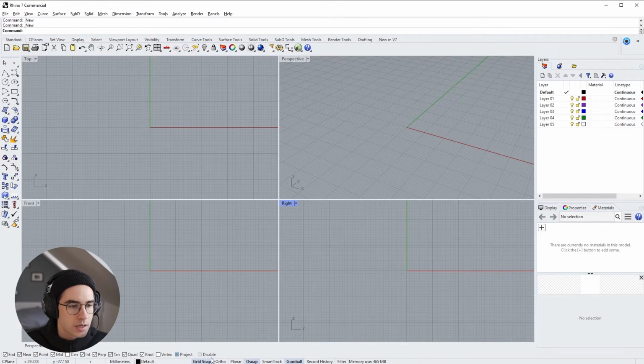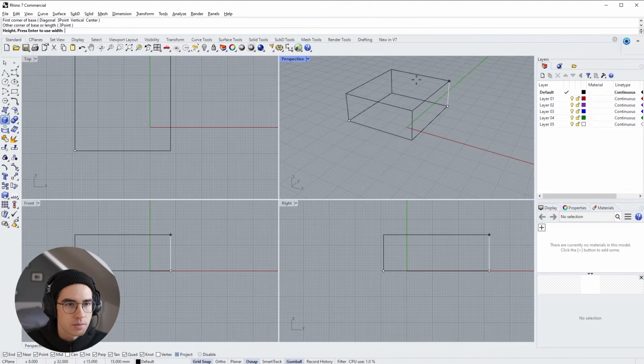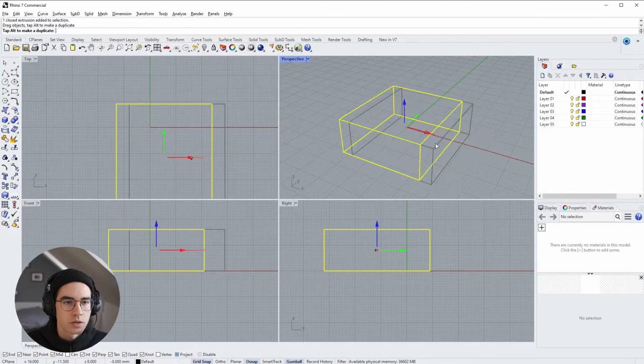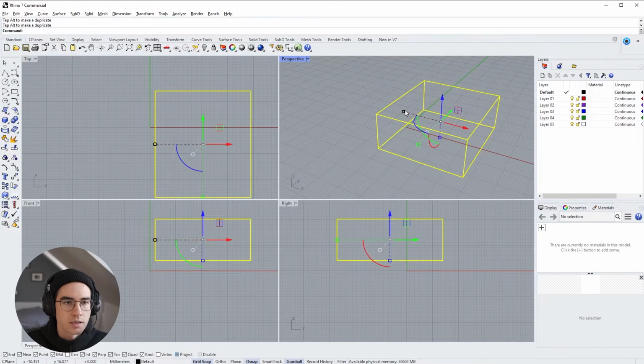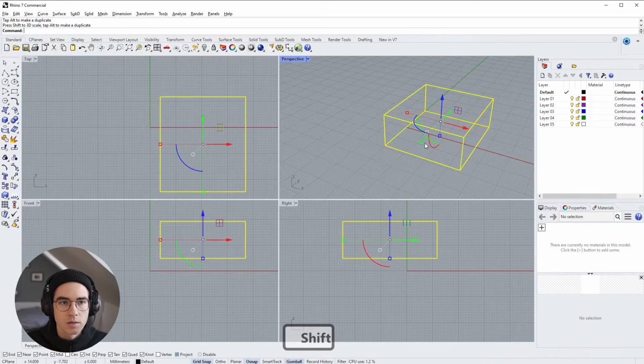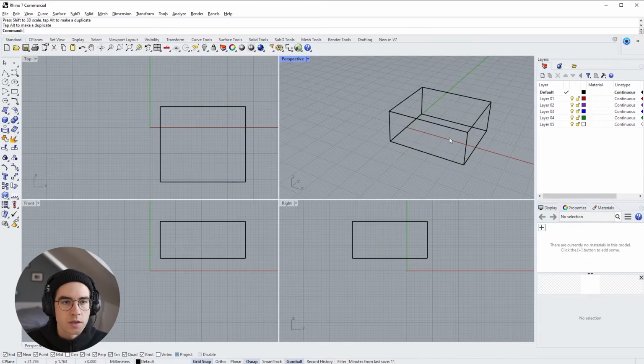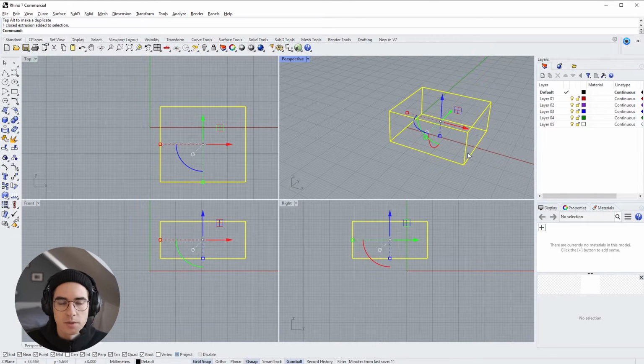For example, I am working with the gumball. So if I have something here, you will see this axis appearing, and this just allows me to move along those different axes and also scale objects in different directions, rotate them. So this kind of makes my life a little bit easier. You can check on and off the gumball down below here, and I think in the Mac version it will be up in the upper toolbar somewhere.